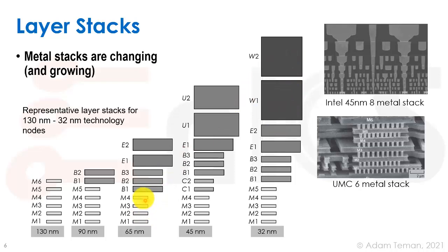So if we have 3 types of layers, we'll call these bottom layers with minimum rules X layers, these Y layers, and these Z layers. Now, you should know that nowadays we have many differences. We have double patterning and quadruple patterning on the lower layers, and so you will have different types of names in these layers. You also have colors of these, but I'm not going into that in this course. So it gets more complex than just X, Y, and Z, but they will also be called with some sort of name. And obviously, when you get your technology PDK, you should look and understand what the different naming conventions are and what types of backend layers you have.